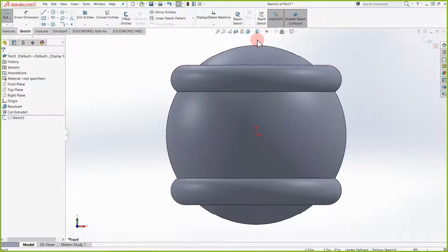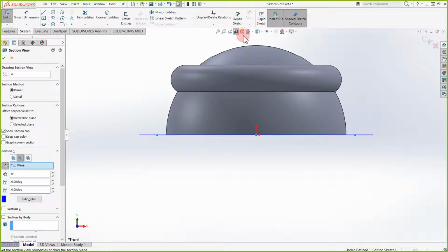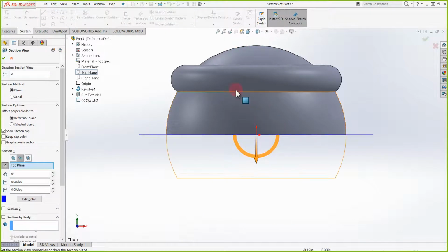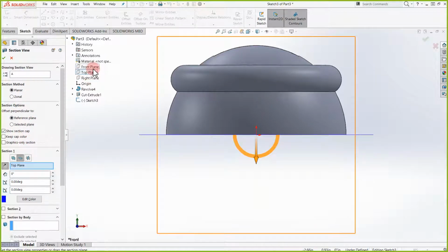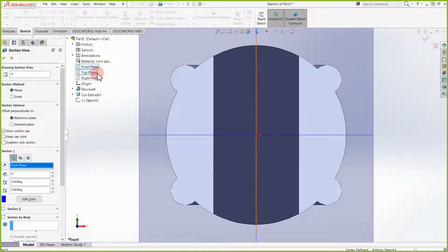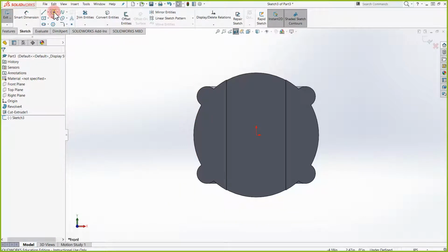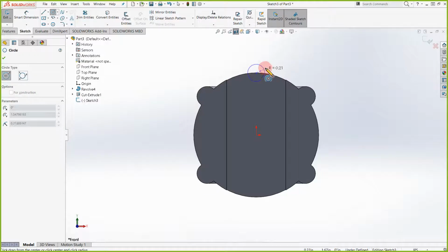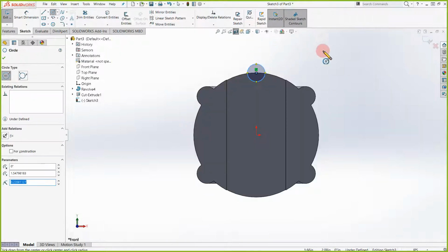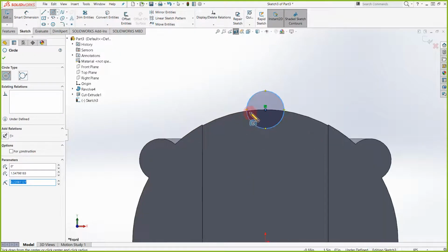Control 8. And we're going to do our section again. So for the section, guys, I click the section on top, and then I can change the view by just clicking over here. See? Top view, right view. I can click on these views to change them as I want. Accept. So now we're making a sketch. Let's make a cutout right here. So let's make this profile like that. What this is going to do is remove this material from my item. Accept it.